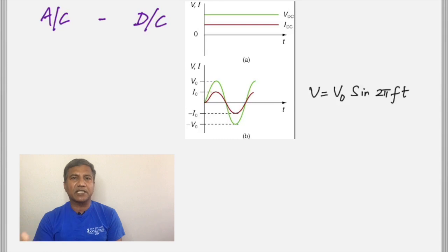It's how many cycles are produced in a second. At home, we have AC, which is distributed at 60 cycles per second, 60. So the frequency could be anything, and when you know the frequency, you can calculate the voltage at any instant by knowing the peak value of the voltage.